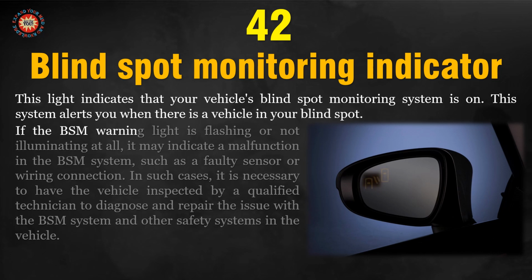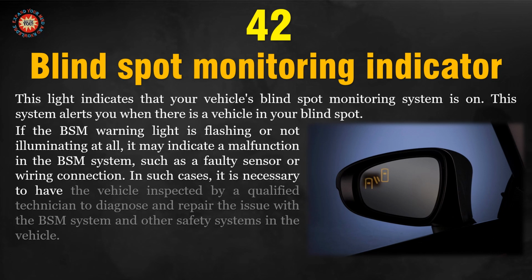If the BSM warning light is flashing or not illuminating at all, it may indicate a malfunction in the BSM system, such as a faulty sensor or wiring connection. In such cases, it is necessary to have the vehicle inspected by a qualified technician to diagnose and repair the issue with the BSM system and other safety systems in the vehicle.